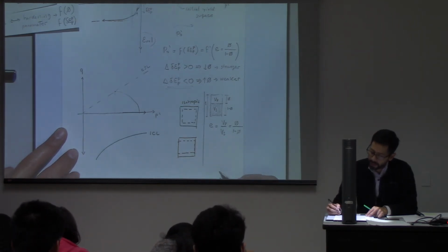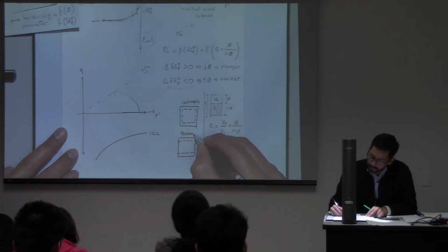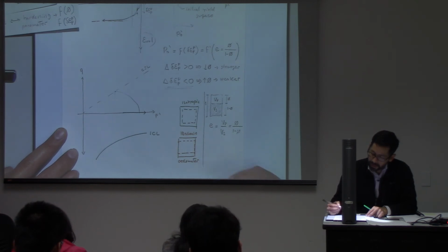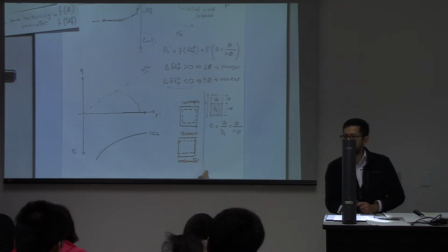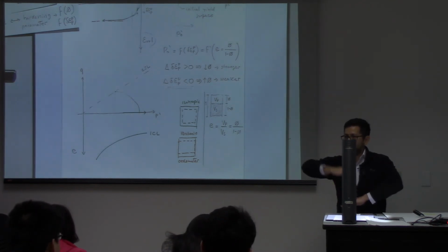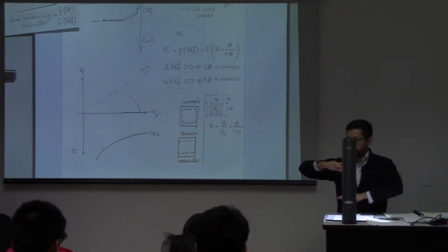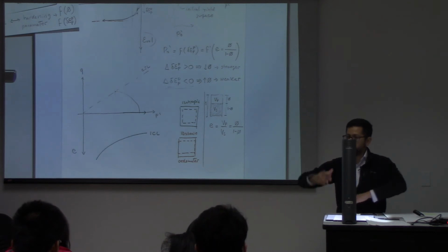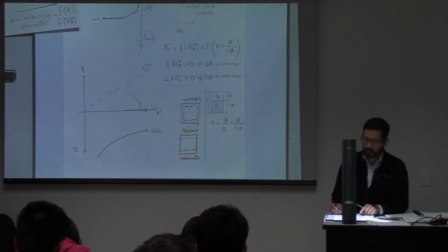And we call that either 1D strain or oedometer test. This is much closer to what happens to sediments in nature as they compact and you have more overburden. And this is also closer to what happens when you, for example, deplete a reservoir, you lower the pore pressure, they compact in this way, not that much in that way.